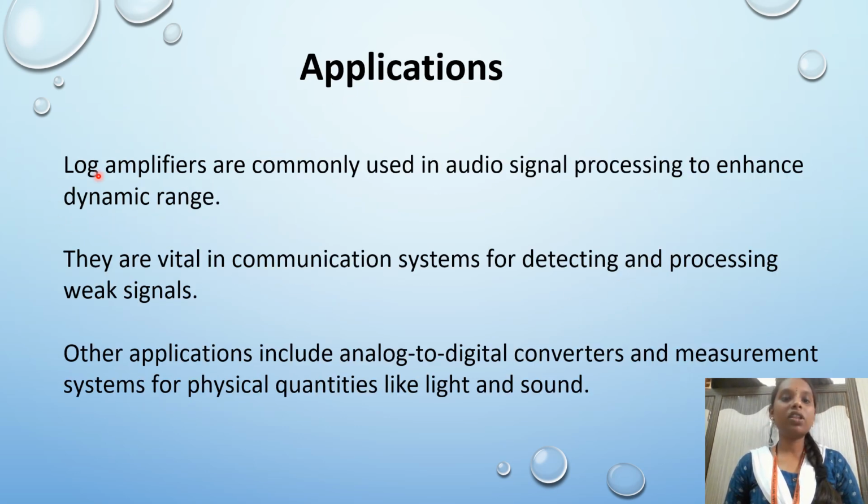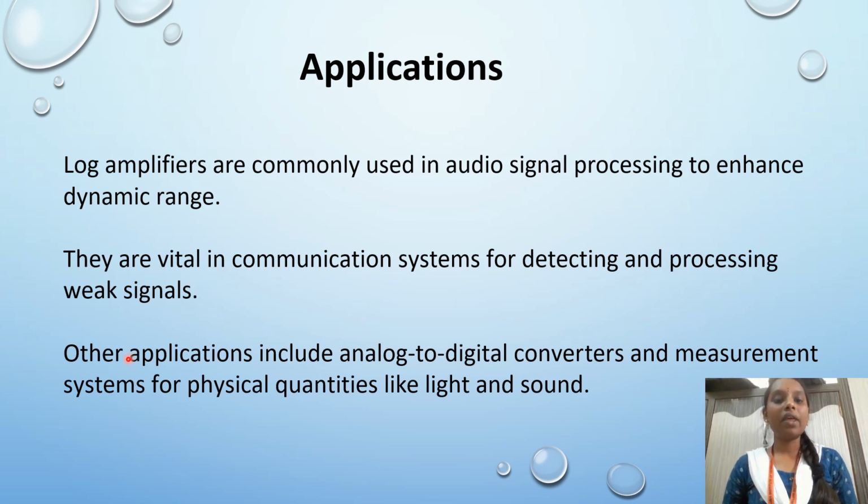Next, applications. What are the applications of log amplifiers? They are commonly used in audio signal processing to enhance dynamic range. They are vital in communication systems for detecting and processing weak signals. Other applications include analog to digital converters and measurement systems for physical quantities like light and sound. These are the applications of log amplifiers.